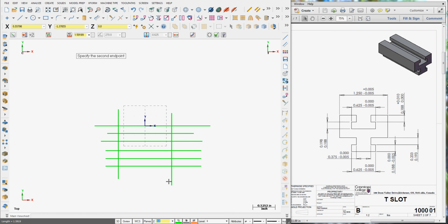So we'll start here, draw a vertical line. Half of 3/8 is what I want, so 0.375 divided by 2. I'll do the negative one, so it'll be negative 0.375 divided by 2. And I am going to stop there and do some trimming just for clarity.